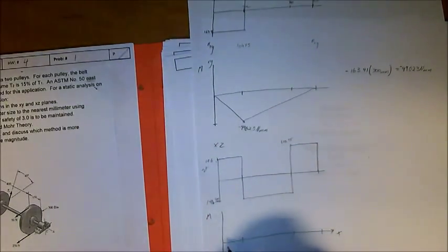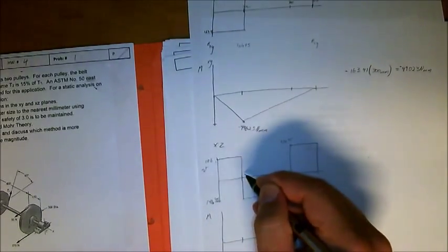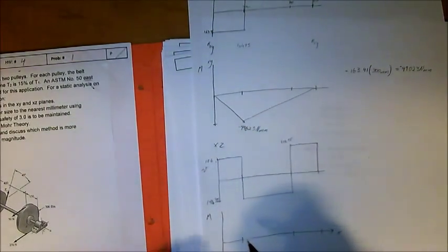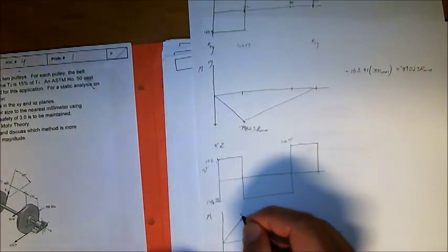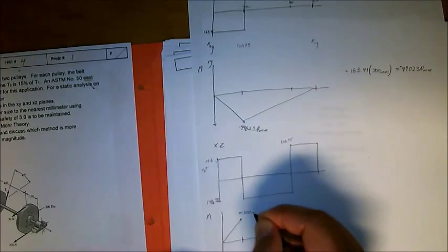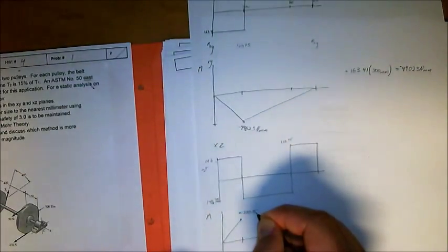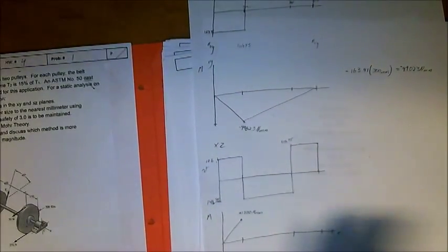We find the maximum value for the moment. That goes up like this, and it is at 31,800 Newton millimeters. I know it's in millimeters. I'm sorry about that. I did that calculation earlier without rounding it up, but you can fix it a little later on in the problem because it's just the power of 3. So this could be 31.8 Newton meters if you want to do it like that.